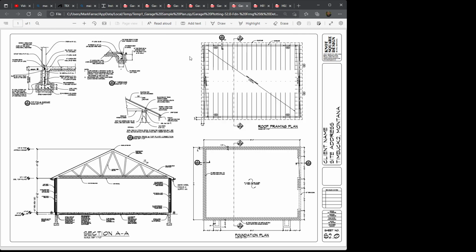Here, we've got just three details. There's not a whole lot to detail out because we have a wall connection for how the truss connects. That's this one here. We need one for where the doors pass through and save some concrete by not pouring that footing all the way through. There's no bearing through there. No reason to dig that full depth, which up here is pretty deep because we've got frost depth to hit. And then I just caught a mistake.